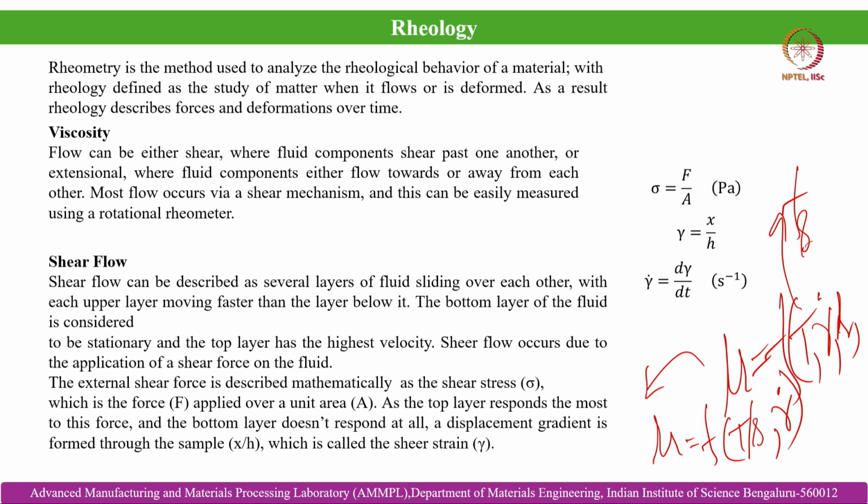So, as a result, rheology describes forces and deformations over time. Viscosity we all know, however, we can discuss again. Flow can be either shear, where fluid components shear past one another. If you assume there is a fluid element, and at the top there is another, there is a relative velocity between these fluid elements. Basically it is just the resistance offered by the fluid towards its motion. Or flow can be where fluid components flow towards or away from each other. Most flow occurs by a shear mechanism, and this can be easily measured using a rotational rheometer.